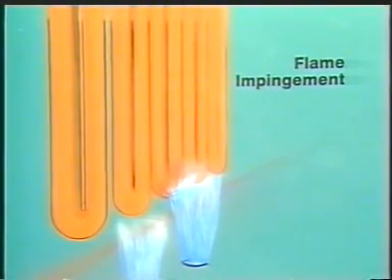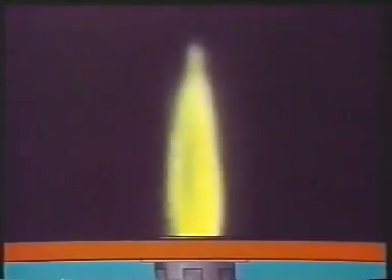The fire should always be kept as uniform in length and size as possible. Let's look at some other undesirable flame patterns and consider the causes. A long, smoky flame is caused by insufficient combustion air or insufficient atomizing steam. The flame may be shortened by increasing primary or secondary air or by increasing atomizing steam. A thin, fluttery oil flame indicates too much atomizing steam is being used.